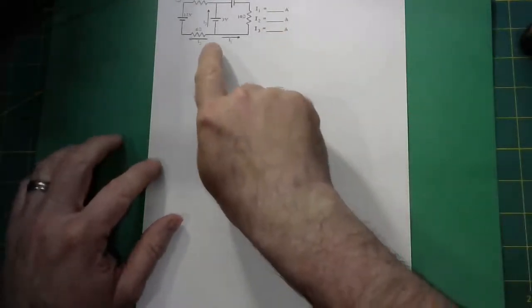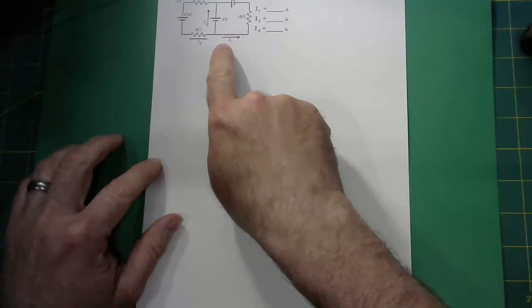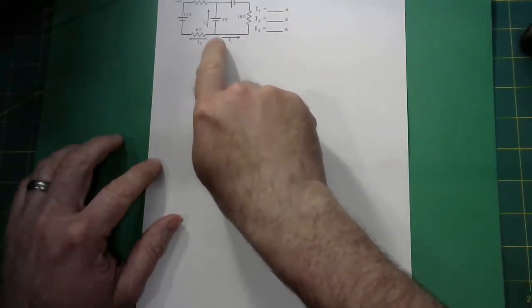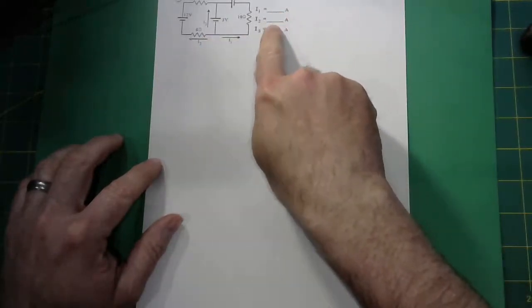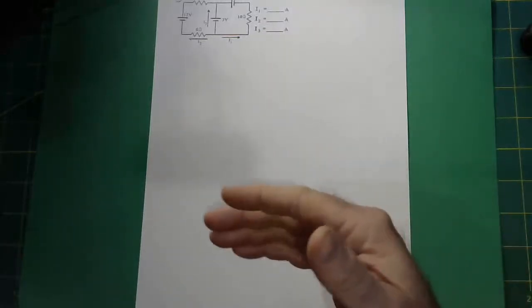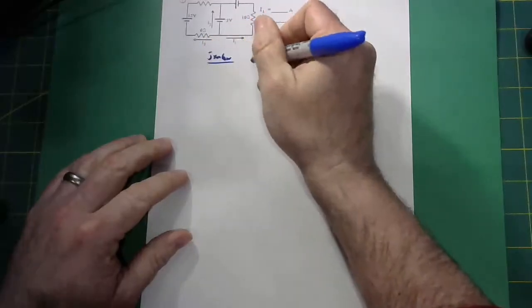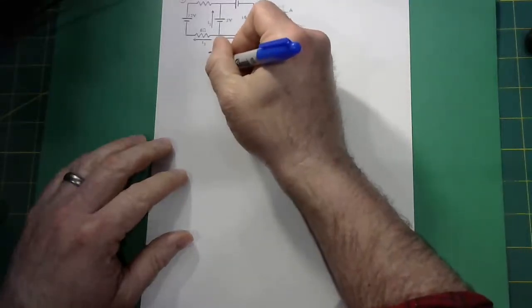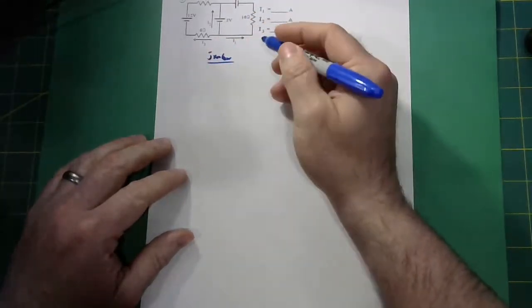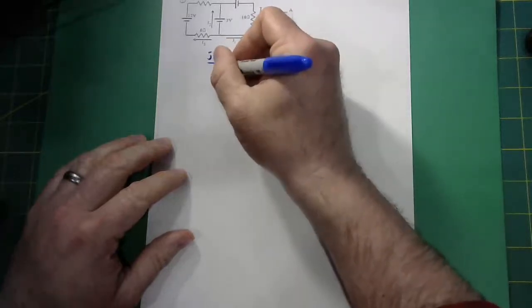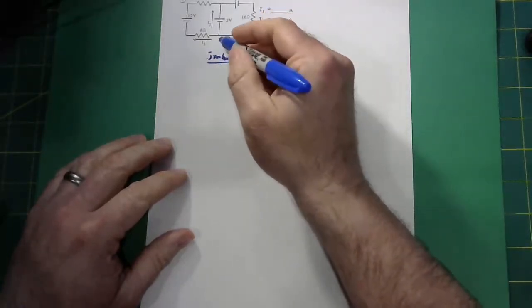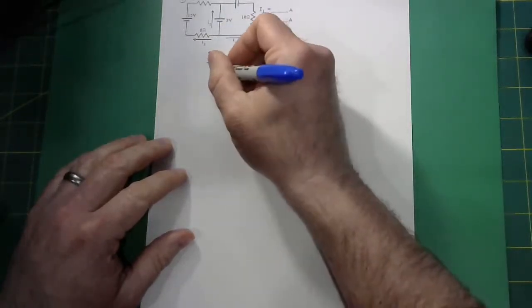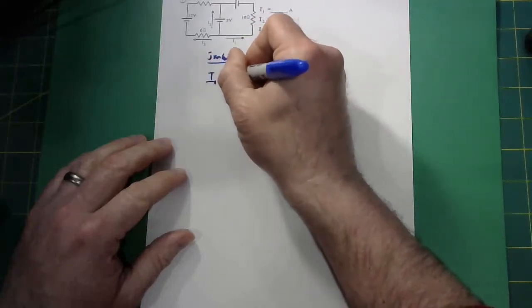And that's all right. The point of this is just so that everyone who does this problem chooses the same notation, so that we all know which one we're talking about when we're talking about current 1, current 2, current 3, and then we all get the same answer. I'm going to do my junction law. We're going to choose the bottom junction where they draw the currents. The sum of the currents going into the junction equals the sum of the currents going out of the junction. There's nothing going into that junction, so it's really just I1, I2, and I3 balancing out, adding up to 0.